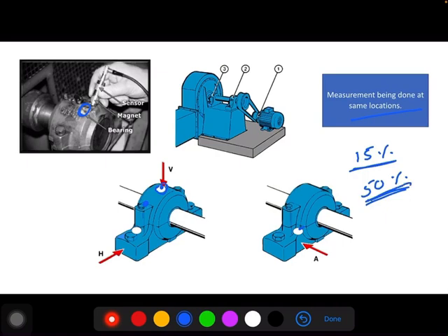You need to find out what the source is. If balancing or alignment is required, you need to take action by taking a proper shutdown. If the increase in vibration above the baseline is 100%, then what happens? You need to shut down the machine and take the proper preventive measure, otherwise it would result in catastrophic failure. So till now I have covered all the ISO standards, what trending analysis you need to make, and what the comparative method is. Okay.